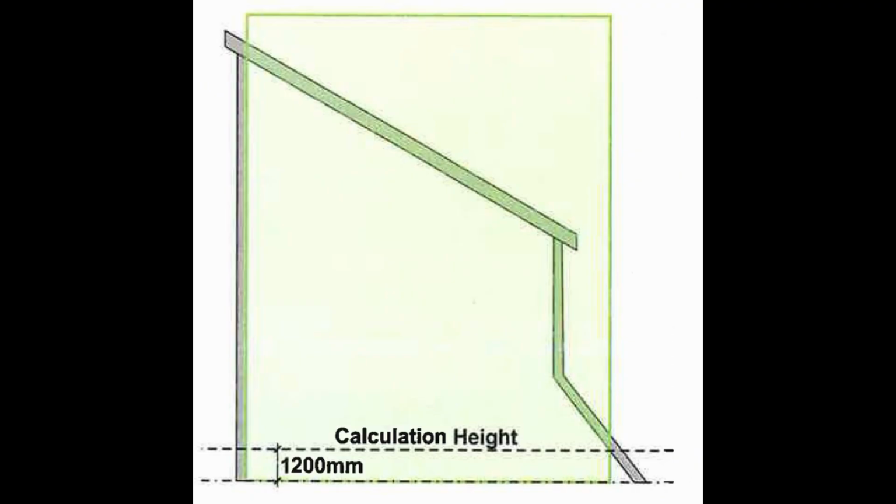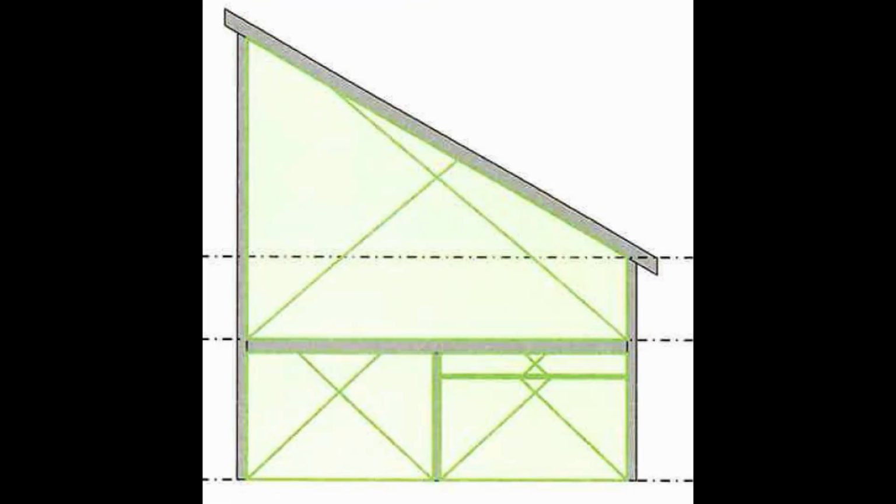Section 5. Area and volume calculation. Revit calculates area and volume based on the calculation height. Rooms default to 1,200 mm, while spaces default to 0 mm. Raising the calculation height can exclude sloped areas, which may be appropriate for architectural regulations, but not for mechanical analysis. For accurate volume calculations, the upper limit of the space must extend above the highest bounding element. If volume computation is disabled for performance reasons, it must be re-enabled before running energy analysis.